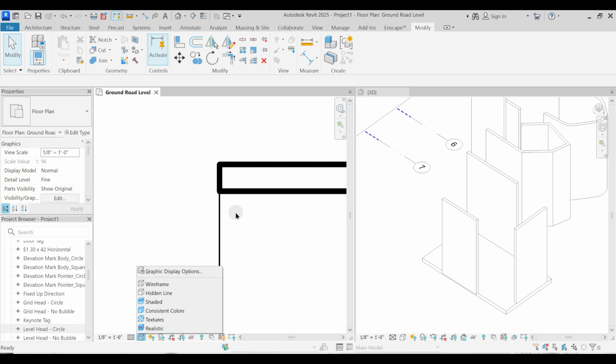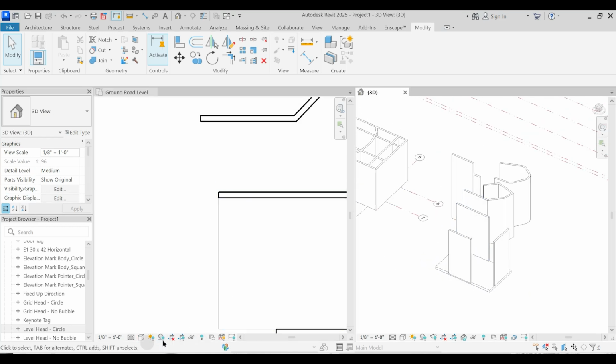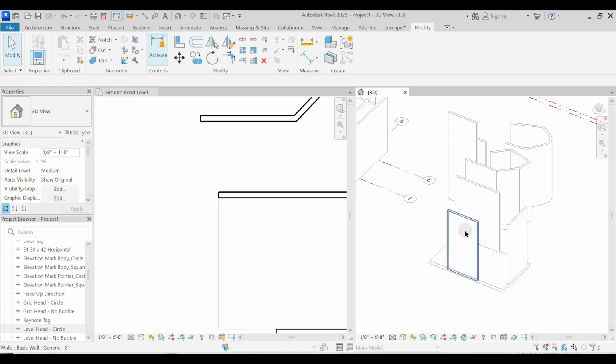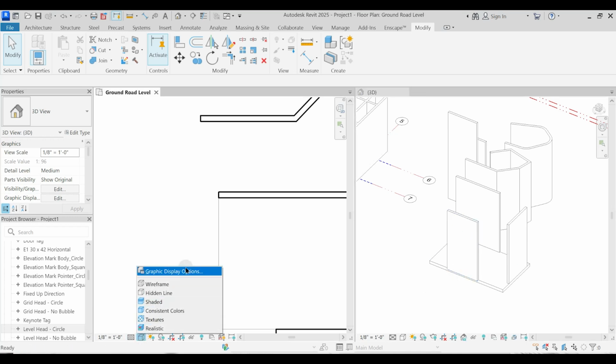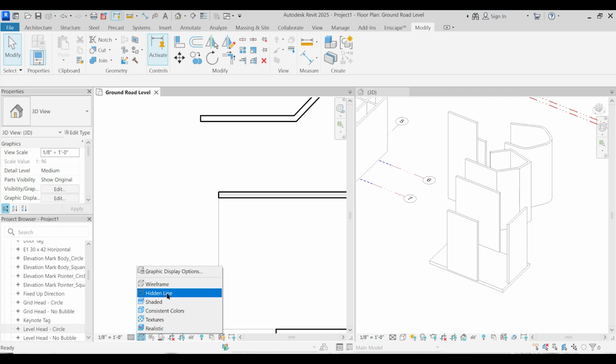In order to proceed further with this wall command, I need to explain what the detail level is and what this visual style is. So Revit में, इसीलिए इसको बॉटम टास्क बार विजिबिलिटी सेटिंग्स कहते हैं क्योंकि ये deals with the visibility of the 3D element, and what do we say, its representation, its on-screen representation. Okay, so with this I will just change this to wireframe here. Sorry, in this view, I will just change to wireframe.